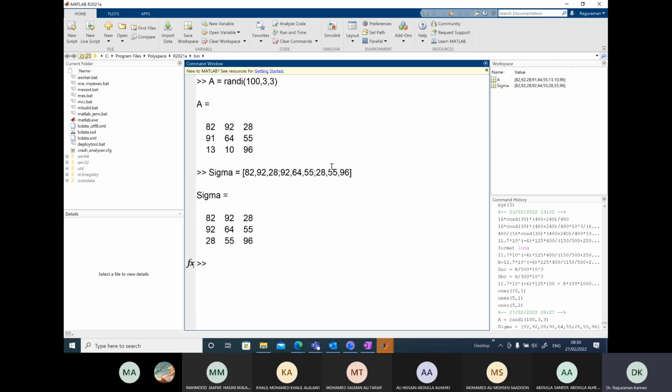Okay, so this is the stress tensor I'm going to consider. It is symmetric, and I want to find the principal stresses and directions for this stress tensor. It's very easy here using MATLAB. We want to call it V, eigenvector. Maybe it is the eigenvalues first.